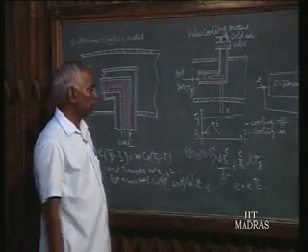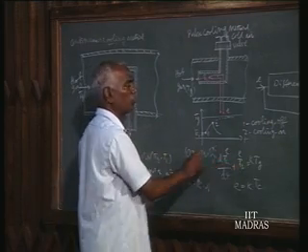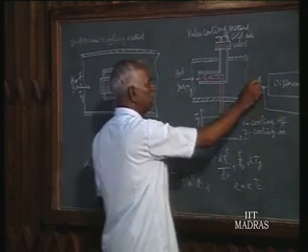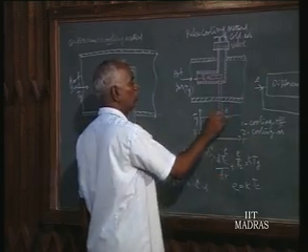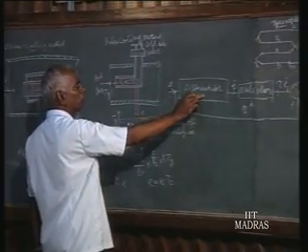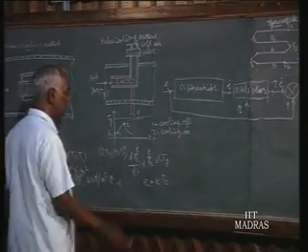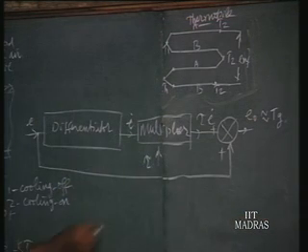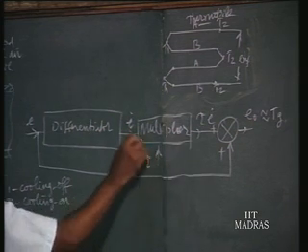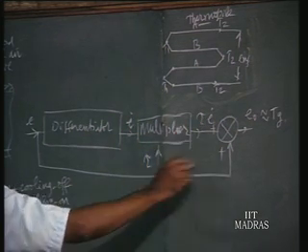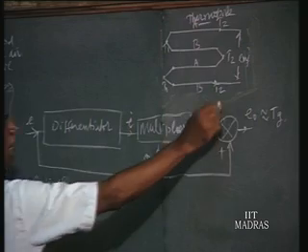hot gas temperature. We realize this mathematical equation in this circuit, that is E proportional to Tc, and dE by dt. For E we have the output voltage, and through a differentiator we get E dot. That is multiplied by tau, proportional to the time constant of the thermocouple element, and tau E dot plus the same E is taken in this adder.